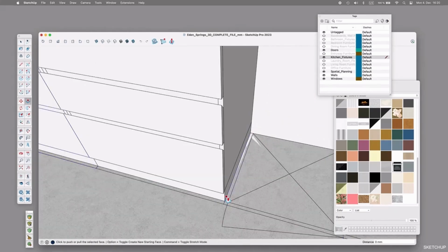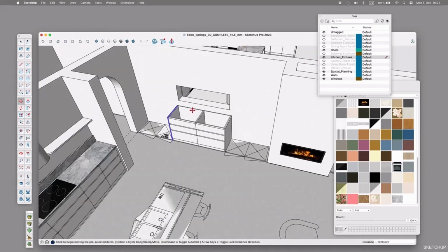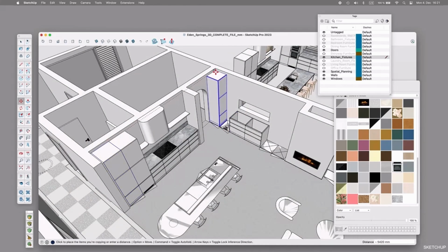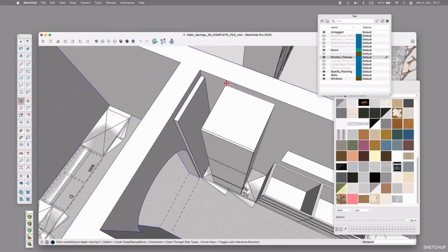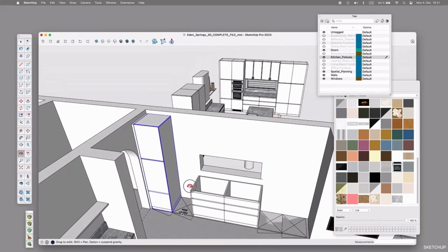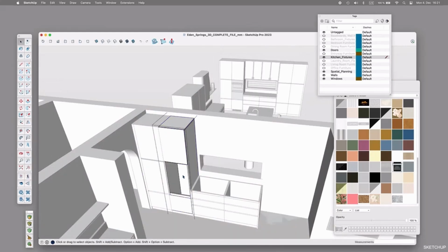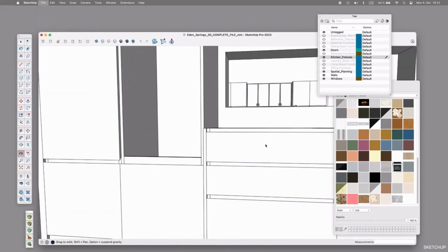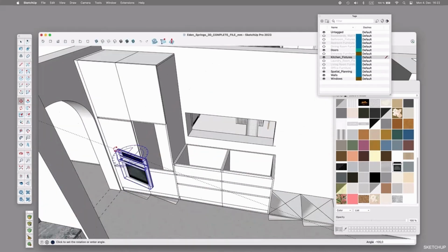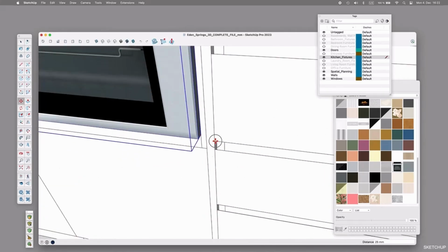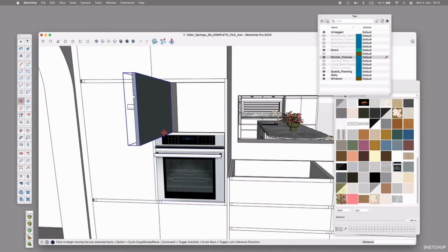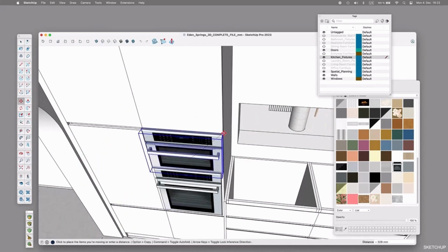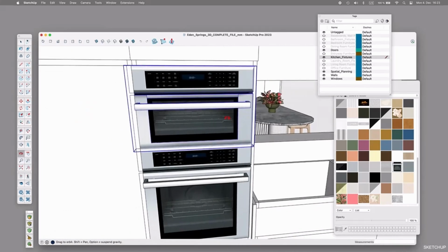You will notice that building the east kitchen wall is much faster, as we basically can copy most of the cabinet boxes I have already created. A quick tip from my side: start collecting your kitchen cabinet modules in a separate SketchUp file so you can reuse them for other kitchen designs. Obviously, you can create modules that have 3 drawers, 2 drawers, or simply different styles. When searching the SketchUp warehouse, I'm sure you will also find plenty of ready-made modules that you can use.